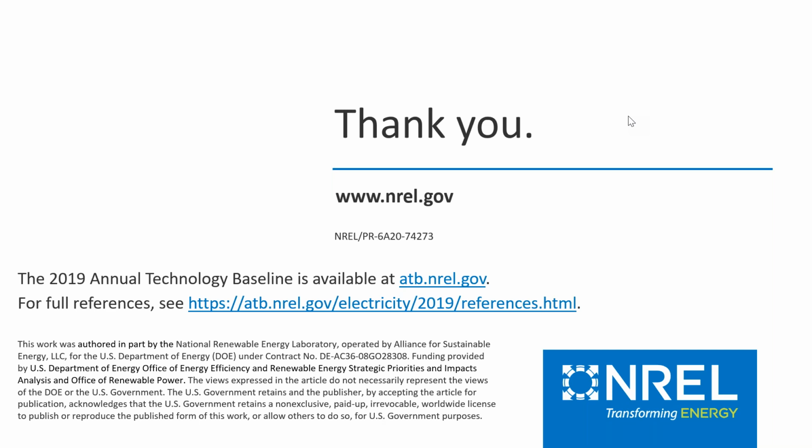One more question on batteries coming in, asking about potential for flow batteries versus lithium-ion. You've seen our representative battery is lithium-ion. There's a lot of activities, and there's also other storage types. You've got pumped hydro, you've got compressed air energy storage, you have flow batteries. There's a lot of types out there. We're not attempting to be comprehensive in any way. Lithium-ion has been the dominant technology deployed recently and appears to be over the near future. Farther than that, it's hard to say what will happen. We haven't weighed in there at all in the ATB, but that could potentially come down the road.